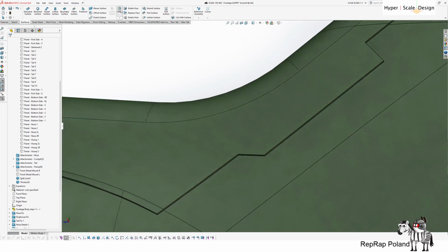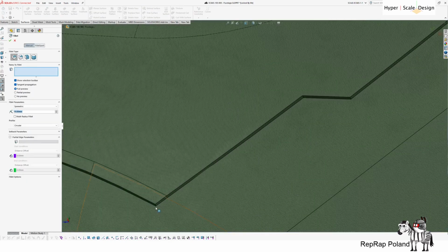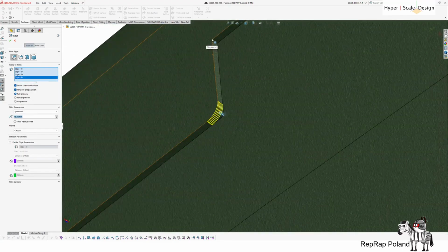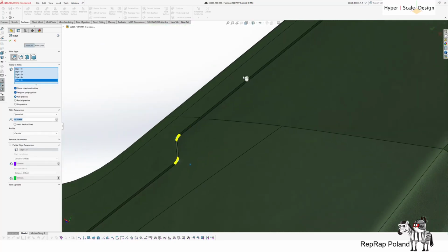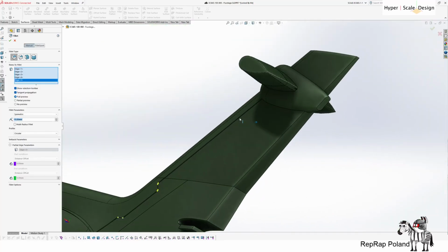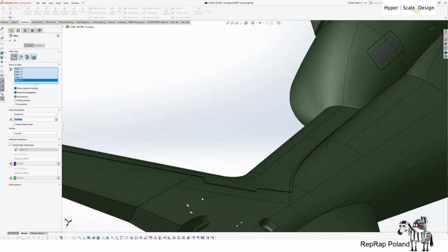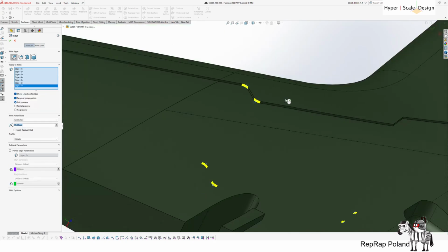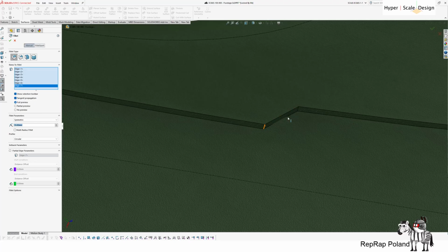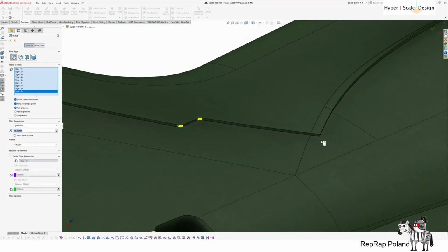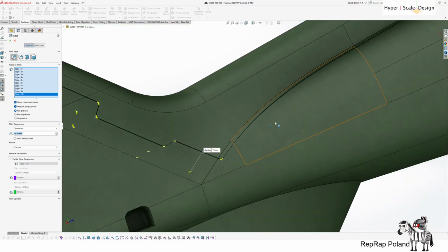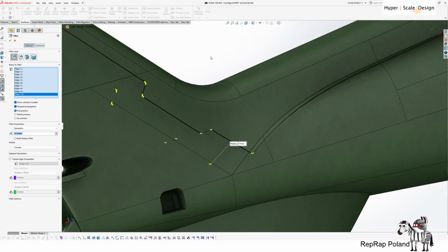The best way to deal with it is just to create fillets. I normally create those fillets after the surface has been thickened. You do not want to create fillets on a sketch you used to trim such a panel, because especially when you're dealing with complex geometry, the projection of the fillet from the sketch will not be the same, depending on the angle of the geometry it is projected on.